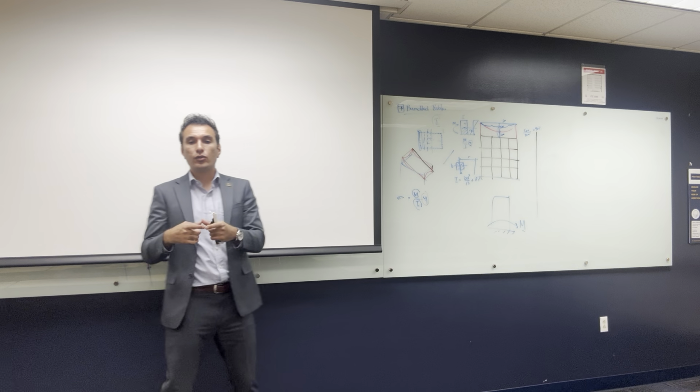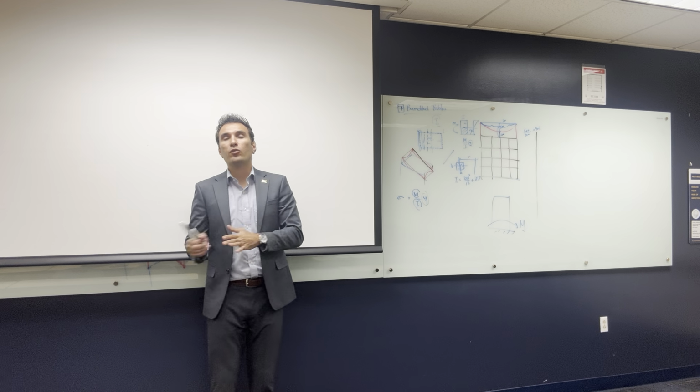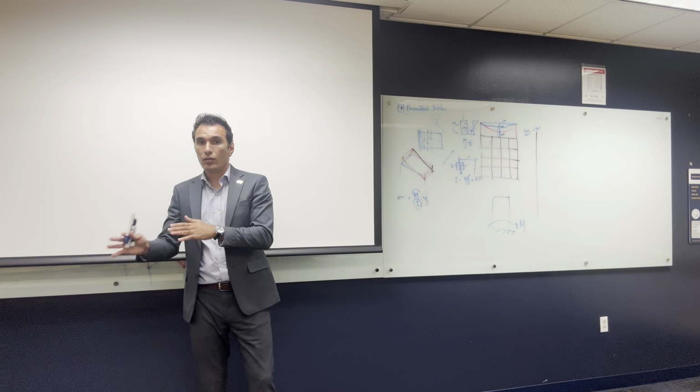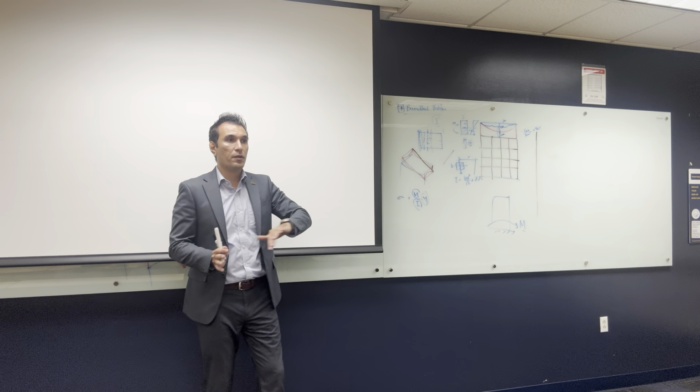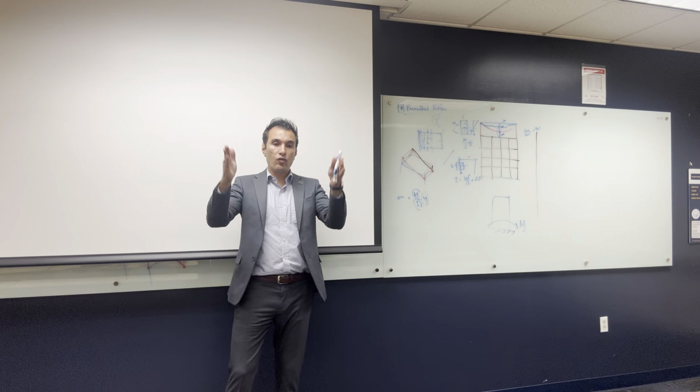And once you are done, you are going to apply your seismic load on maybe 10 or 12 models, depending on your group size. So let's say you are going to apply the loads on a building that has columns of 1 meter. The columns dimension for each group is going to be constant. We'll see. Maybe you will change the column dimensions. But at the end, once you do your 12 models that have different column and beam dimensions, with outriggers and without outriggers, you are going to end up showing me graphs.